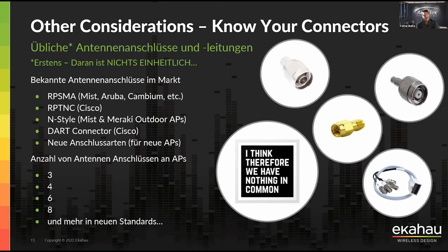So depending on what the radio is, make sure you take the time to know the connector and how many connector ports. Otherwise, I'm just telling you, you're going to have a problem when you get out to the site and you're going to be like, these things don't connect together. Also, if you're going to add cable extensions, or lightning protection, which is very important if you're going to be outdoors, make sure all those connectors match up. I still get a piece of paper and write out all the connections to make sure they all match together, so when I get to the site, it works properly.